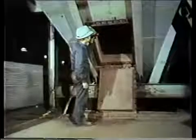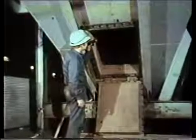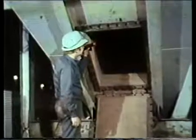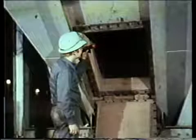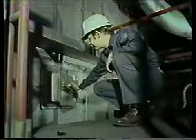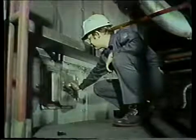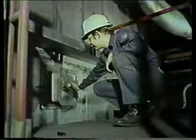Once fireside cleaning is finished, the boiler must be closed up. Before you close each door, check inside again to make sure that no one is left inside the boiler. You can never be too careful about that. Also, make sure that all equipment has been removed. All doors that were opened before you started the boiler inspection and cleaning must be closed. A door that is left open will let hot gases out of the boiler, and this might start a fire.